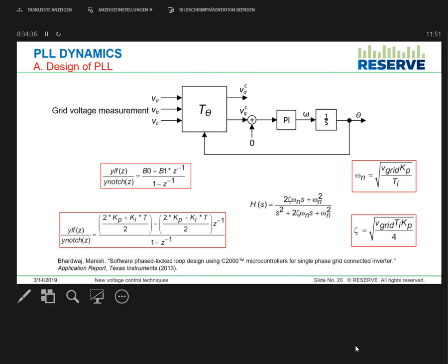And so based on the continuous time controller gains that you designed, based on these principles and the sampling time that you use, you can immediately have your PLL design in this way. One thing that I, of course, assumed is we are just looking at balanced scenarios, because the unbalanced case is even a little bit more complicated than this, and there are a lot of references. You can just go and look into that. But this is just the basic idea of PLL, and even this is highly challenging to design.